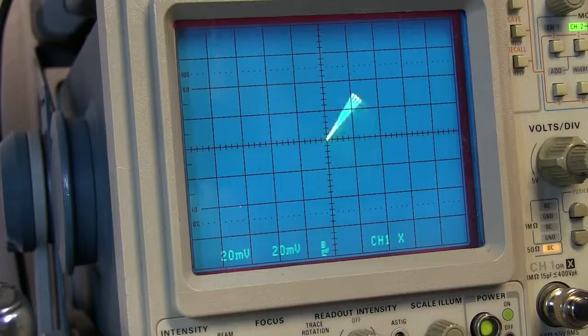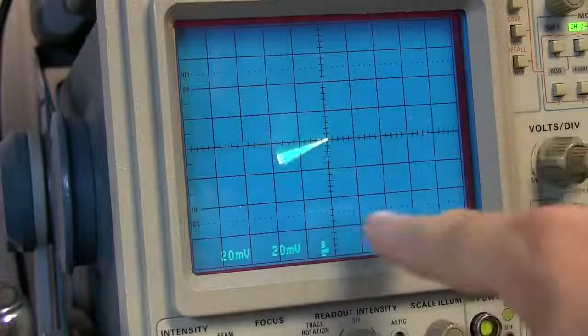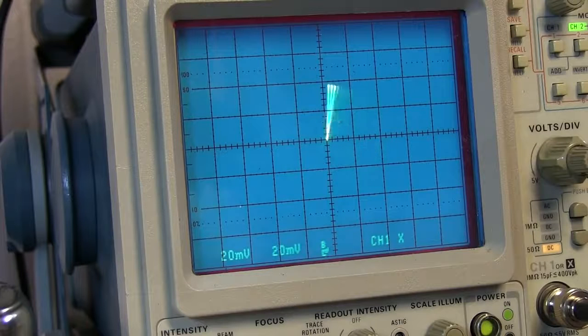So I hope you enjoyed this part 2 video on how some of the basic modulation types like AM, FM, certainly FSK, even single sideband can be generated, or I should say, modulated and demodulated using baseband IQ signals, and how those are represented in essentially the phasor diagram. I think it's a nice convenient way of understanding what's going on with the IQ signals. And in today's software-defined radios, most of the time the IQ signal generation and IQ signal analysis is all done in software, making it very, very flexible to generate and demodulate various types of modulated signals.